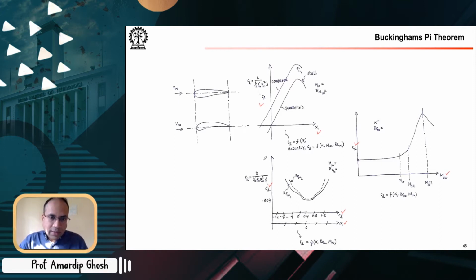So this is drag divided by half rho u square times S, where S is the reference area, in this case the planform area, and we get this CD plot. Remember that small c d is essentially for the airfoil, or for the infinite wing. So here we are showing the drag coefficient for the airfoil as a function of alpha or CL.